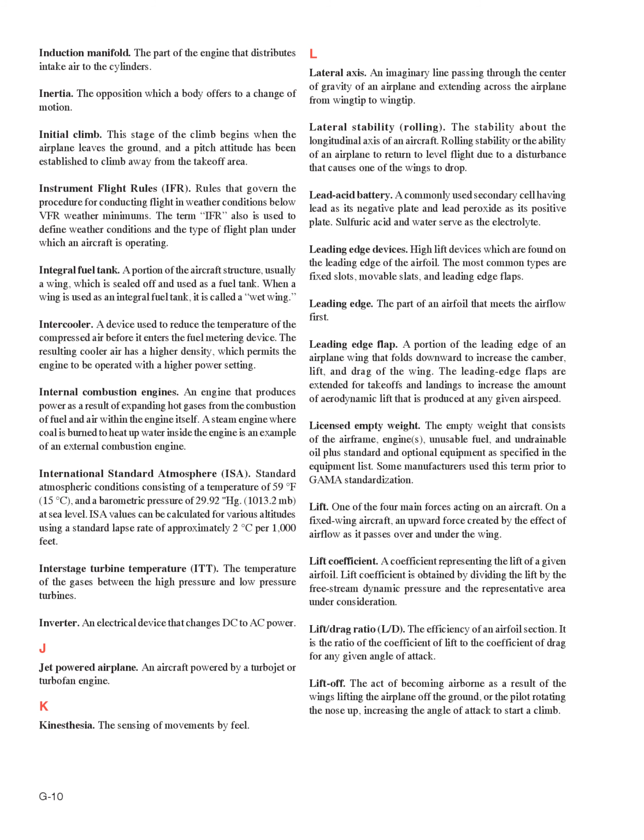Licensed empty weight. The empty weight that consists of the airframe, engines, unusable fuel, and undrainable oil plus standard and optional equipment as specified in the equipment list. Some manufacturers use this term prior to GAMA standardization.